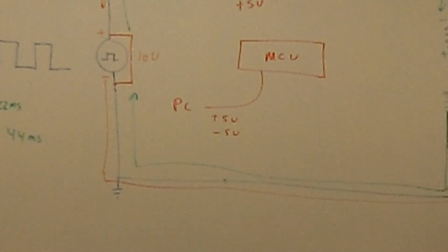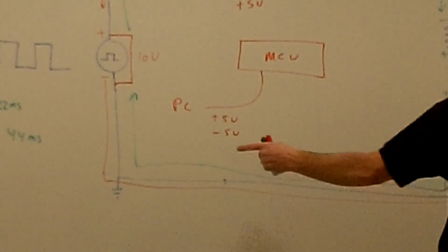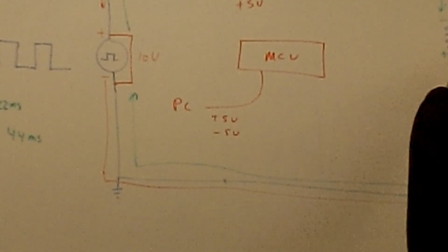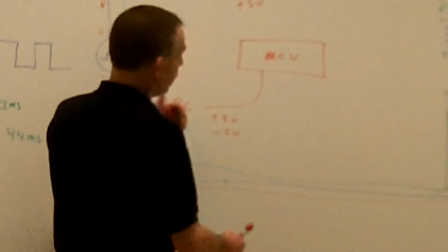They charge and discharge a capacitor. Then they come off the output of the resistor side to get the plus and negative 5 volts that we need for this. And so they call these charging pumps. They charge up a capacitor and then they pump it back in.